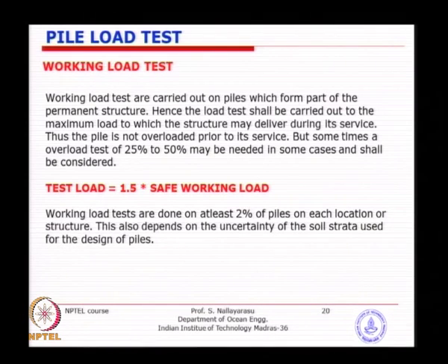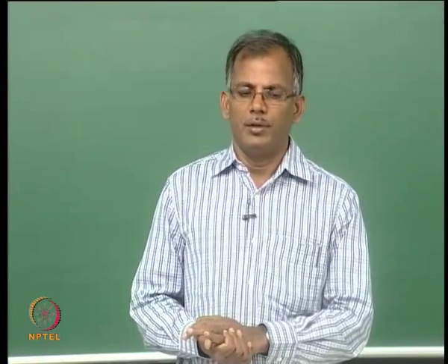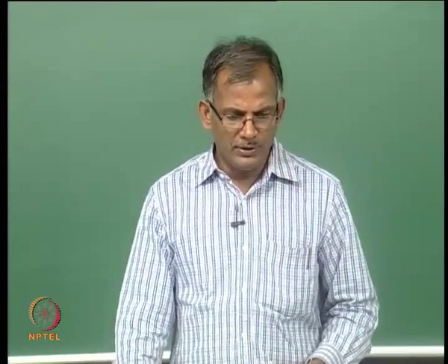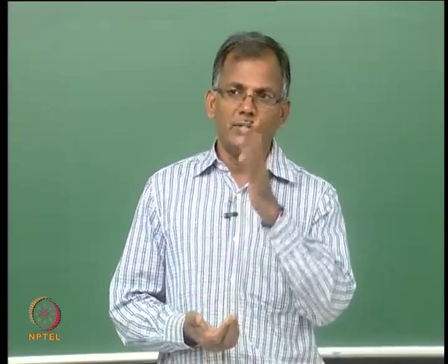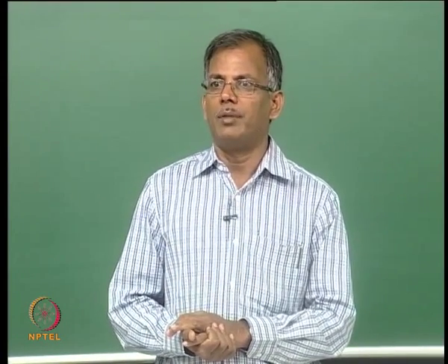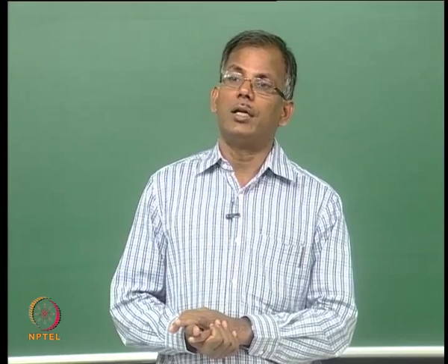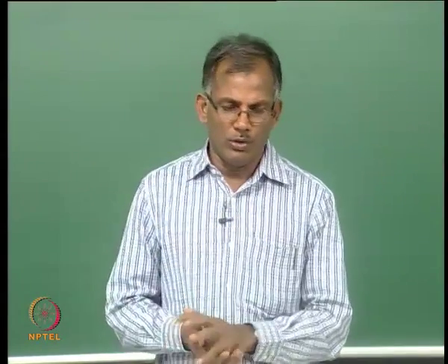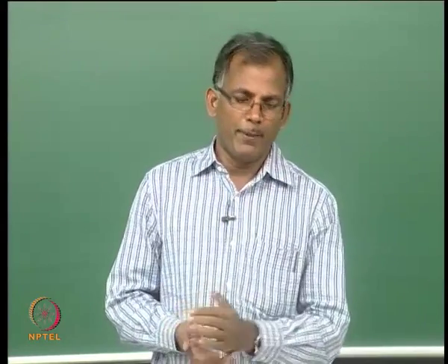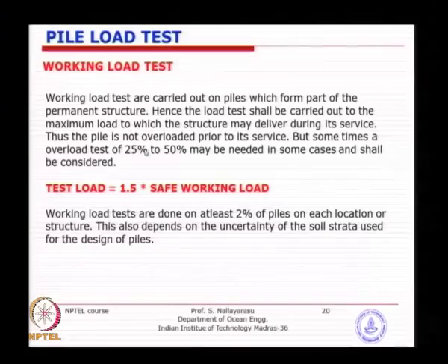Again, it depends on how much design margin is available, and sometimes we reduce to 25%, which we normally call the overload test. Even for mechanical devices nowadays, the working load test alone is not acceptable. You have to go for a slight overload, because if the load exceeds the working load even by a slight amount, it should not fail. So, that is why the overload test is about 25 to 50%.